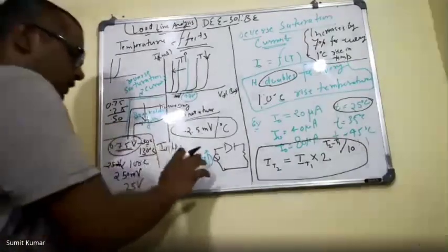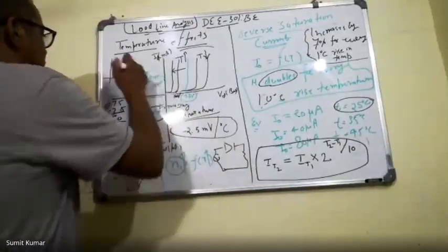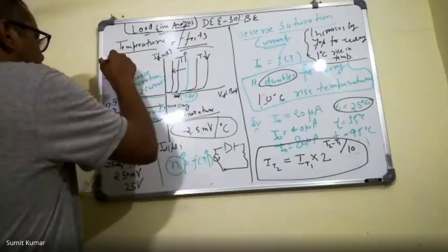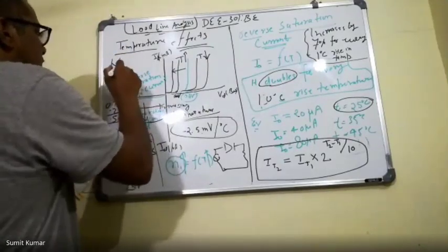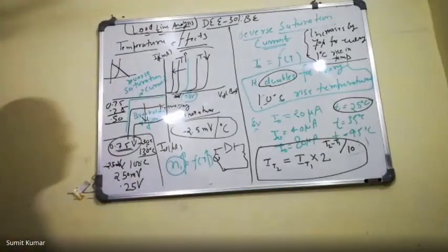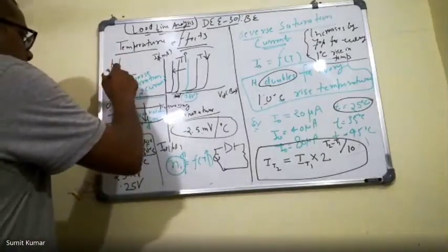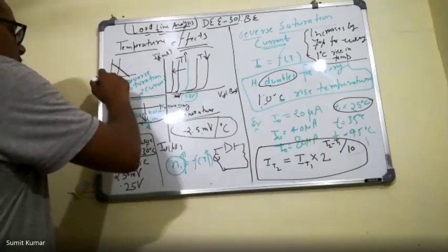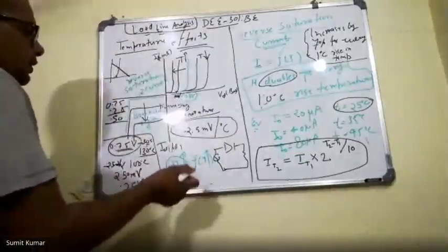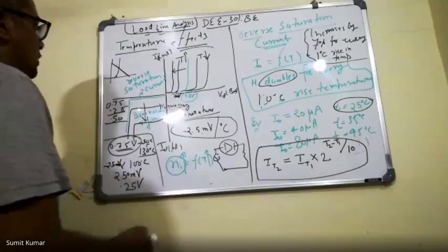By using this battery and resistor, which is a linear element, I can find a line here, and this will be the solution. This is how you can obtain the solution for the circuit, because the characteristic is non-linear. This characteristic is known to us, and with it we will try to find the operating point, meaning the current flowing through the diode and the voltage across the diode.